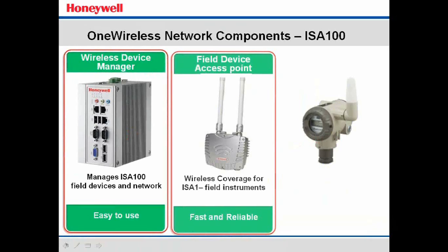The top 2, one of them faces the wireless side and one of them faces the process control side. That's a hard firewall. There is no concept of traffic flow through that firewall. I'll use Modbus for example. The Modbus table is built in this wireless device manager. So the data is posted to the Modbus register by the attribute, and then when the DCS asks for a register number, the value is provided to the DCS. There is no sense of a flow of the PV through the wireless device manager. It's a kind of a server situation when it comes to Modbus.